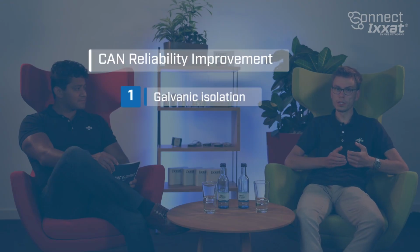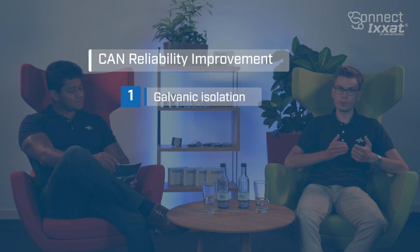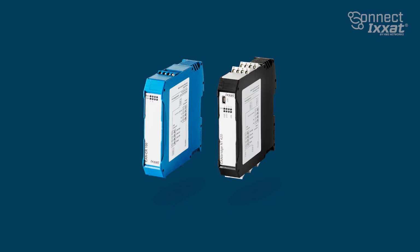So, how does galvanic isolation play into all of this? Galvanic isolation is particularly important within environments with high electromagnetic interferences. By using devices like the Ixxat CAN repeaters or CAN bridge, you can isolate, for example, frequency converters from the rest of the network, which helps to prevent noise and ensures cleaner signal transmissions.